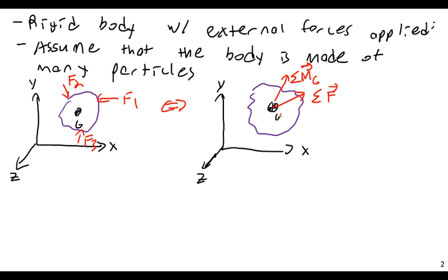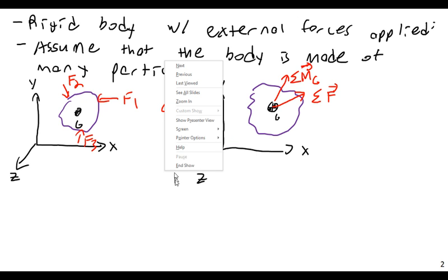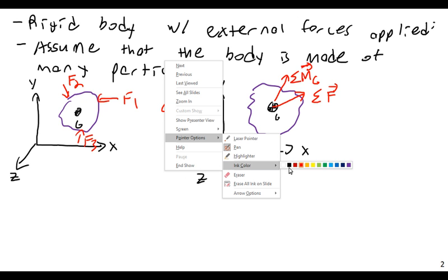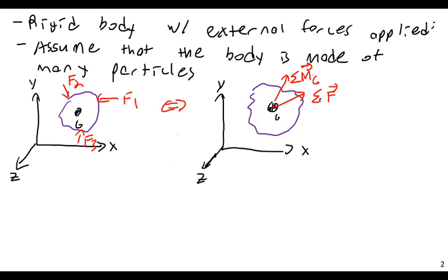So again, I can reduce this system of forces, and this is a three-dimensional system, not a two-dimensional, but again, I can say that these arbitrary forces can be collapsed to just two things: a net sum of translational forces and a rotational force about a translational vector about the center of gravity of the object.